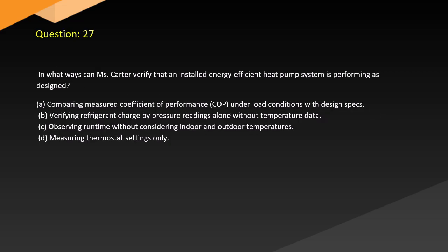Question 27. In what way might Carter verify that an installed energy-efficient heat pump system is performing as designed? A. Comparing measured coefficient of performance, COP, under load conditions with design specs. B. Verifying refrigerant charge by pressure readings alone without temperature data. C. Observing runtime without considering indoor and outdoor temperatures. D. Measuring thermostat settings only.